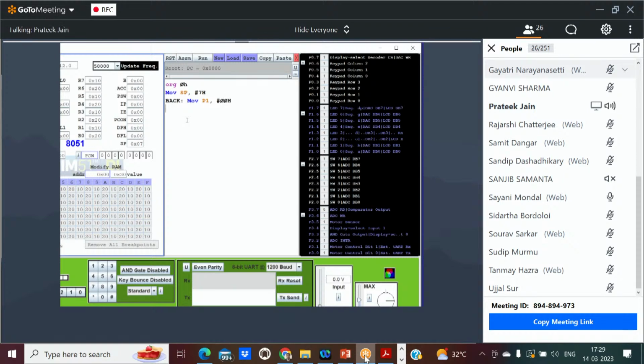After that, we have to assign the next instruction, which is ACALL DELAY, that is wait for some time. This is the command to provide the significant delay. Now you can see this ACALL DELAY means wait for some time. And again, we have to apply the higher value, that is we send FFH, the maximum value on port 1, the high level of the square wave.